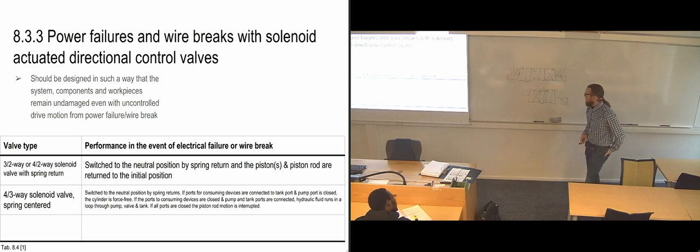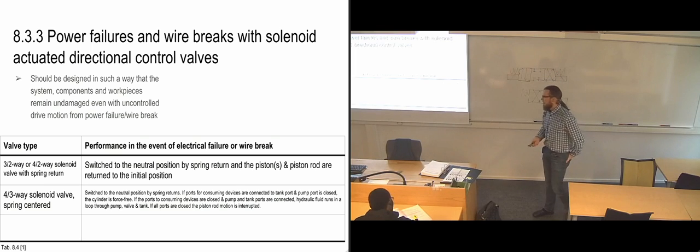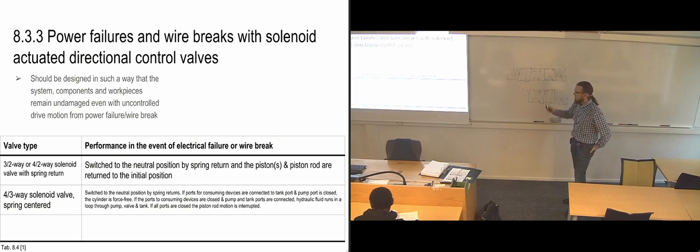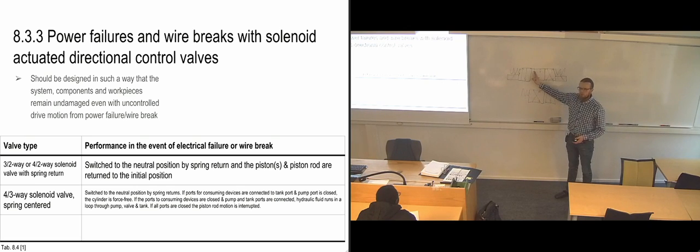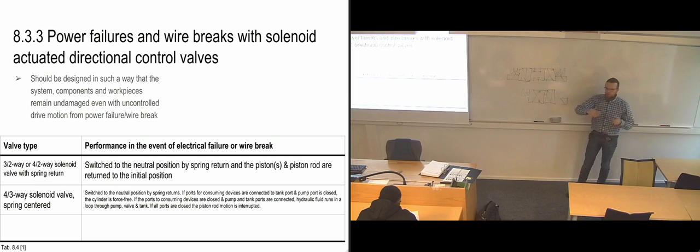So for a 4-3 way, the one we have up here, the springs are going to center it, of course. So then we just need to think about what's going to happen when we are centering it. Do we have a pump that's being run on a different power system? So, for an example, is the pump run by a separate diesel engine or something like that, while the solenoids are pulling power off the power grid? So if we then have a power failure, the pump is going to continue running. But if you shut down this one for a while, then the pump is going to be pushing with maximum pressure against the closed port here. So then you could have a problem.